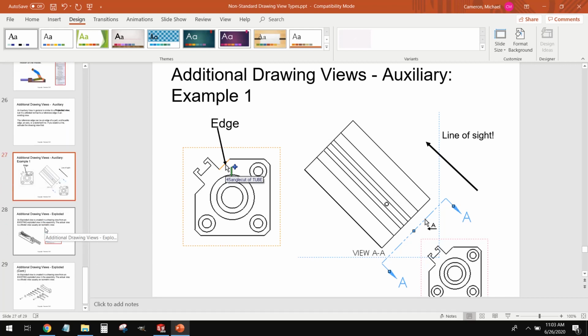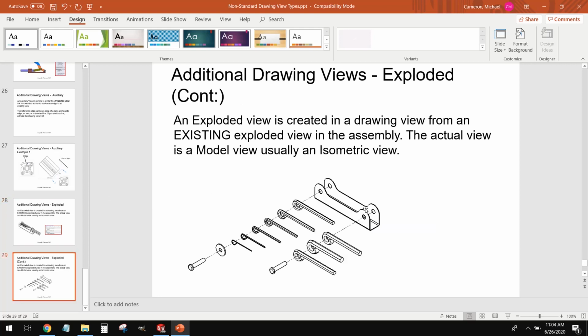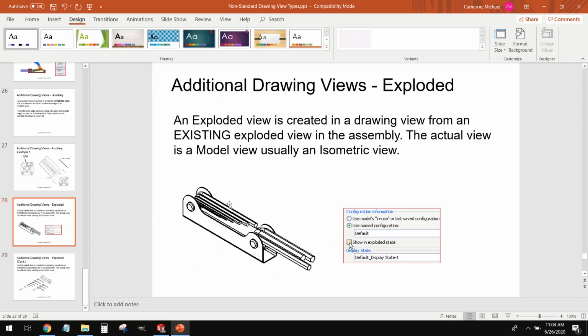And then finally, we have what's called an exploded view. And if you have ever seen IKEA furniture, you have seen an exploded view. This view right here, we have a pretty decent sense of everything that goes into it. But some of these finer details get lost. So what we can do is we can take this and explode it out so we can see all the parts that go into this wrench. And it lays out the order and the assembly process generally of how these parts go together. That way, we have much better idea of what goes into this than we would from this view.